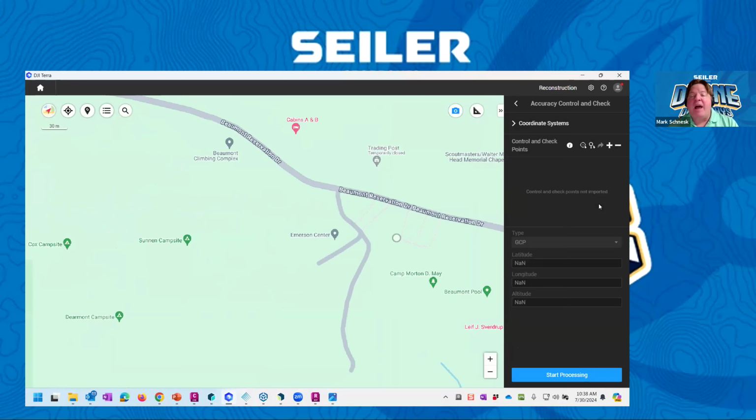I can apply ground control just like I did in photogrammetry. Certain software allow it, some don't. DJI Terra and LP360 allow you to add ground control in. For DJI Terra, it will give you just basically a checkpoint. Once it creates the point cloud, it will tell you the elevation difference between your point cloud average elevation at the XY versus the control point and give you a residual report. Or I can do a best fit vertical adjustment, so it may raise or lower the point cloud to best fit those points. Something like LP360, on the other hand, can do a full 3D transformation, rotate, and scale based upon your control points. And you'd pick them out just like you would ground control in photogrammetry.